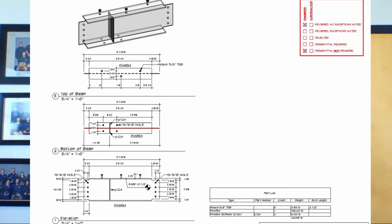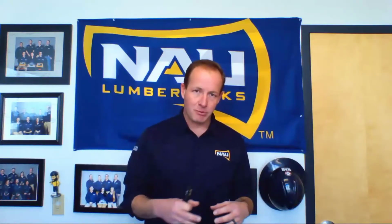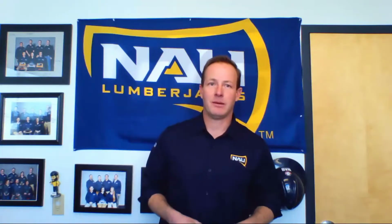It'll show the weld plates on it and what it needs to be welded to, and the weld size and the weld location and the attachment detail for the joist or for the girder. And it'll show all of those things on the shop drawings. So much more detail. Detail for fabrication, detail for installation, and also all of the locations so that the architect and engineer can verify that those locations are exactly where they want it per their drawings, and that it is being fabricated and installed the way they want it to be fabricated and installed.